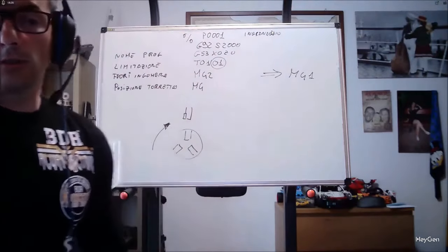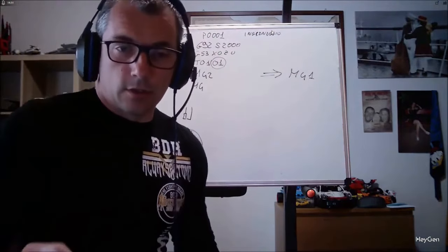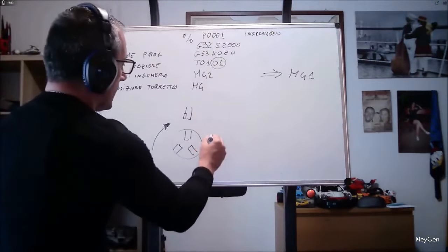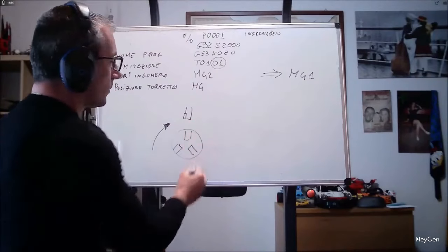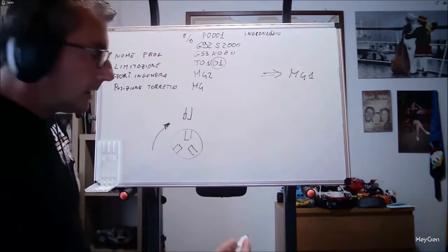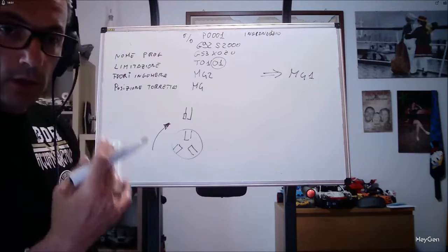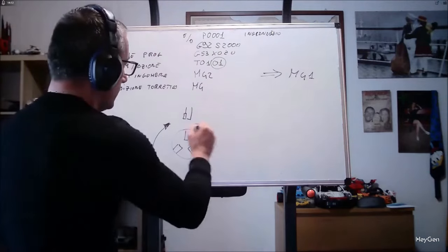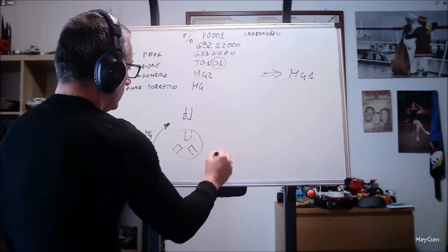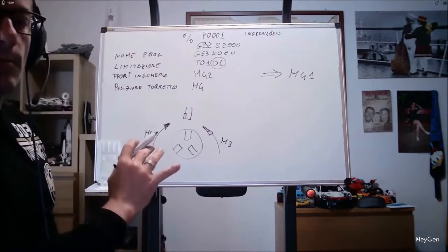There are some manuals that say to look at it from the back of the lathe, so counterclockwise. Once you know this on a lathe, it also applies everywhere. It doesn't change. If you want to make it turn in reverse because you've mounted an insert incorrectly, you're threading or drilling because the bits normally turn in reverse. So, always check the tools and pay attention when you input M3 and M4. Use your eyes, don't trust it blindly, or else the parts will jump, which is a pleasure.